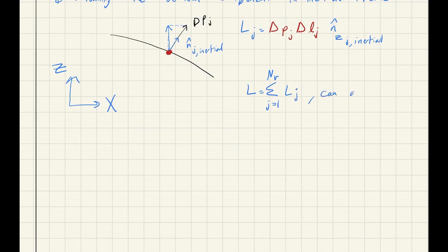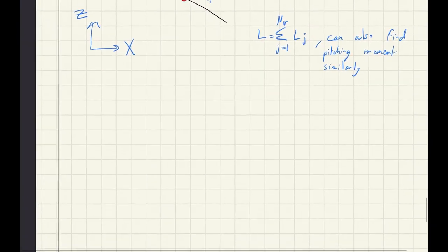And we can also find the pitching moment similarly. So if you know where the force is at each panel and how much it is, you can calculate a moment about any arbitrary pitch axis you want.